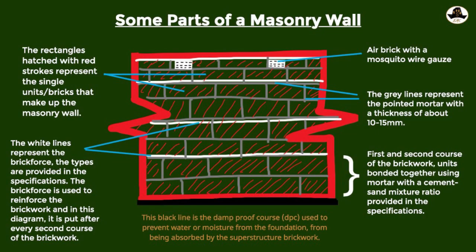So for walls, we have many types of walls. We have monolithic walls, curtain walls, framed walls, masonry walls, which is the most commonly used type of wall for residential buildings. That's the masonry wall. But before we put the walls, we first have to put the DPC, what we call damp proof course. DPC is put on top of the brickwork that we saw in the substructure, and then on top of it we then build that masonry wall.